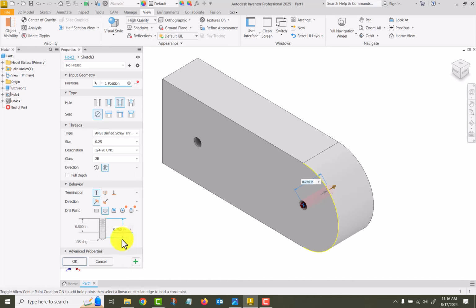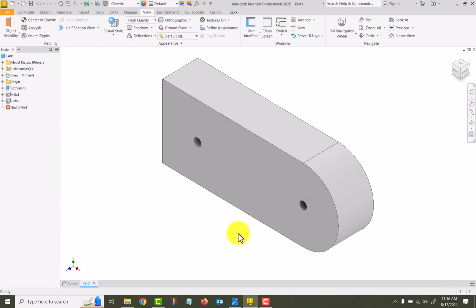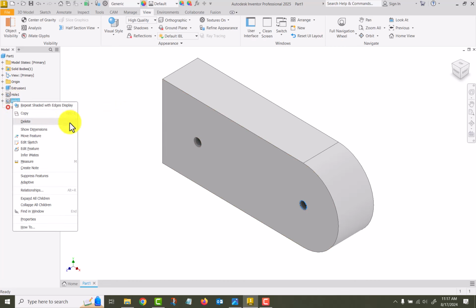So with this, we've got a depth of the hole, and then we've got a thread depth. One of the things about threads is when you have a blind hole like this, we'll say the hole is 0.75 deep, they can't create threads all the way to the bottom of the hole. There's always a set distance that will be unthreaded, or the threads will not be fully formed. And we'll cover that once you get into the 1111 class. But in a case like this, you would set your thread depth and your hole depth. Okay. All right.